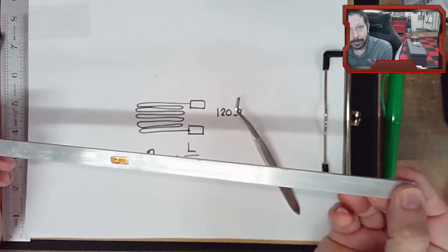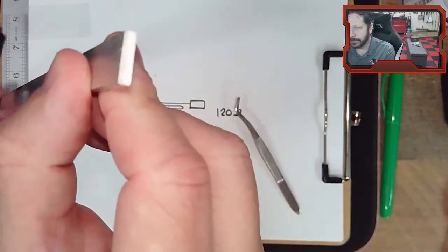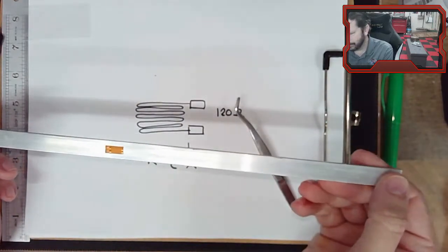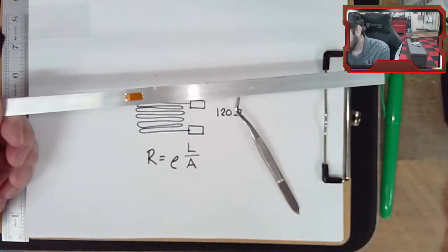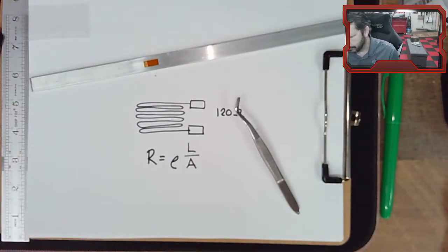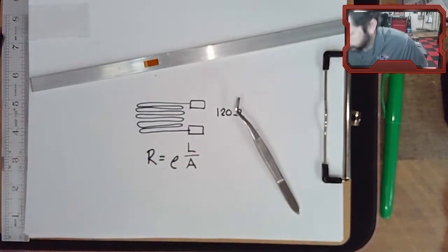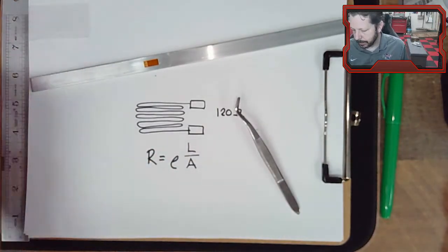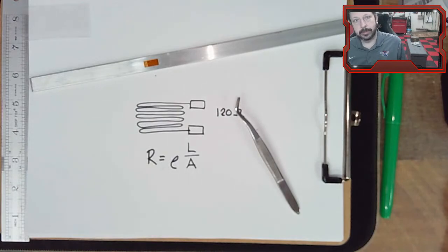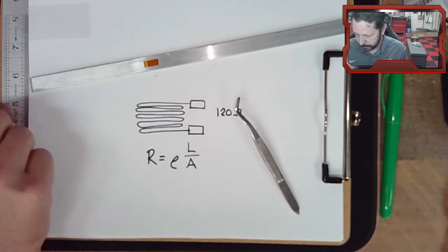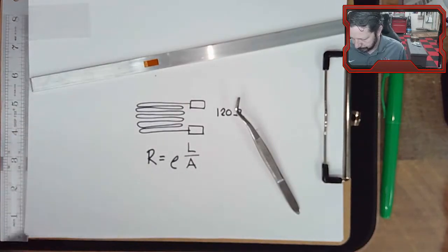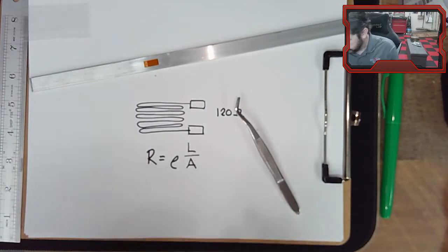So if we know E, the modulus of elasticity, and the moment of inertia for the beam, and we know the strain in there, then we can back out the force that must have created that strain. Actually, I guess we could do the stress, and then Hooke's law will tell us the strain, and the stress will tell us the force, and back it out that way. We'll get to that later.